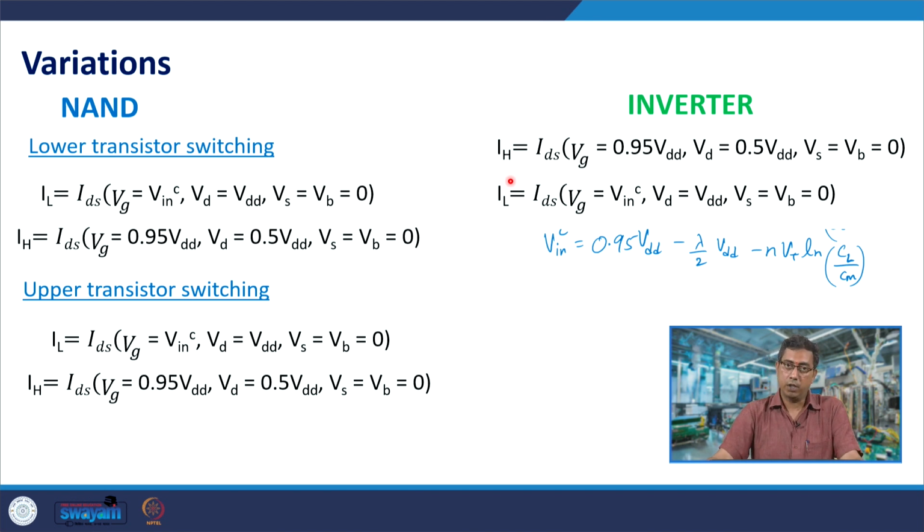So, the change in logical effort can be computed from change in threshold voltage, mobility and VDD, and therefore also temperature. So, the impact of PVT variations on logical effort can directly be computed using this approach.